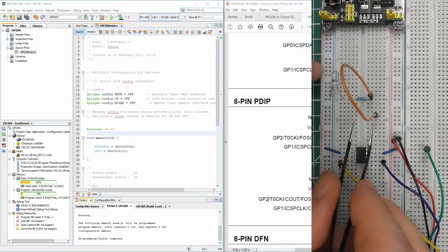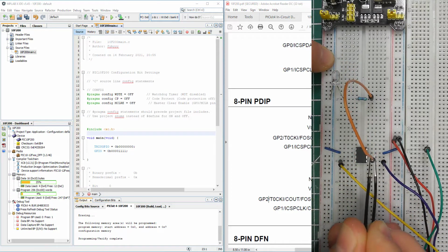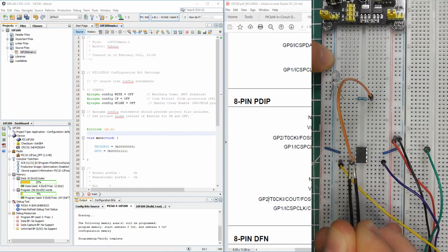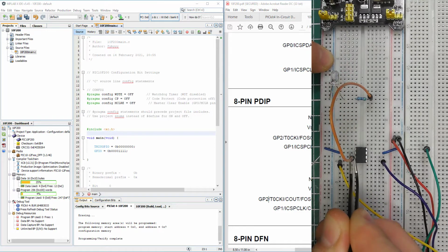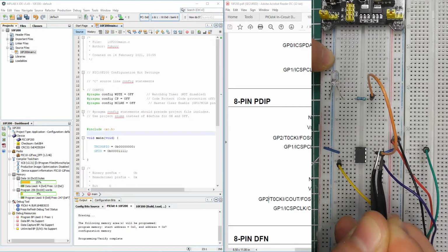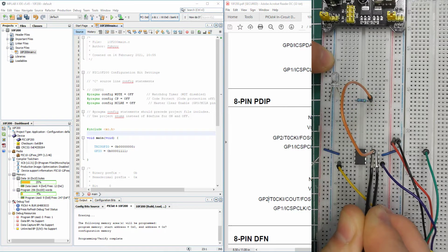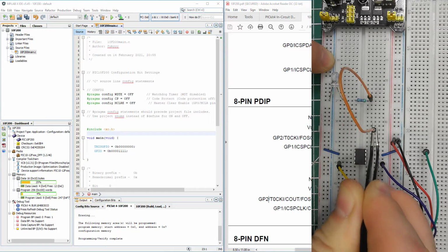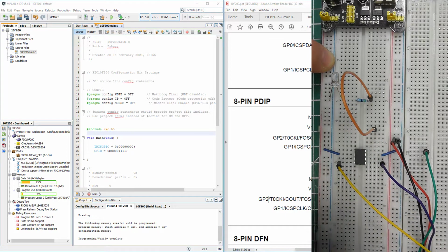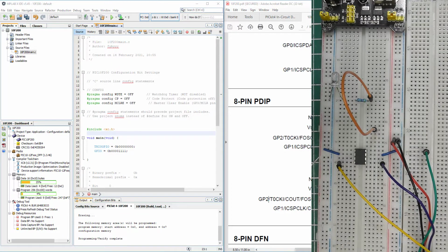Okay, so again let's check with this LED jumper. GP0, have we still got 1? Yes. GP1, yep. GP2, we know about this, there are still more things to be done. And now GP3, we know this pin can be used only as an input. However, there was still a weak signal before. Now it's clear because we've switched off the master clear reset on that pin, and it cannot be used as a reset anymore. So this pin is now input only, it's waiting for the information.